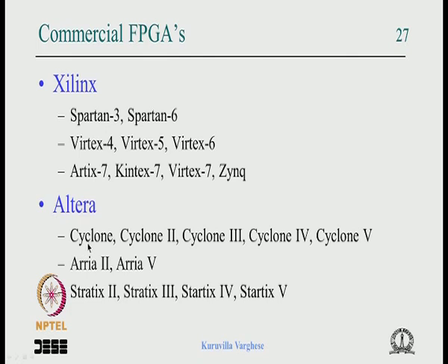When it comes to Altera, they have the Cyclone kind of low cost devices. Again, that doesn't mean it is low performance or low complexity. They have the Arria series and Stratix series, which are the complex versions of these devices. They have soft core processors called Nios that can be implemented in these devices, and Xilinx has soft cores like MicroBlaze. Soft core means the design is available in terms of Verilog or VHDL code. They have something called PicoBlaze, which is an 8-bit microcontroller, and the MicroBlaze is a soft core 32-bit RISC processor. Similarly, Altera has the Nios 2 32-bit RISC soft core processor.